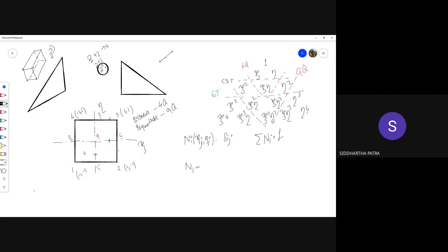Okay, there is no way I can reduce that to lesser than 4 lines. Okay, not for all shape functions at least, which means because I need to have 4 lines, therefore I'll be getting one term that has cumulative power of xi and eta to be 4. Can you see this?